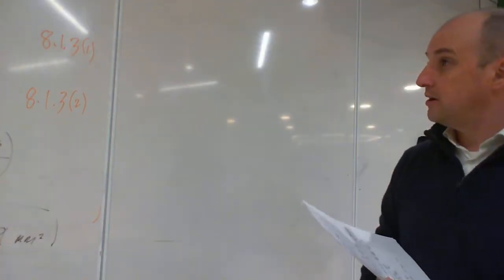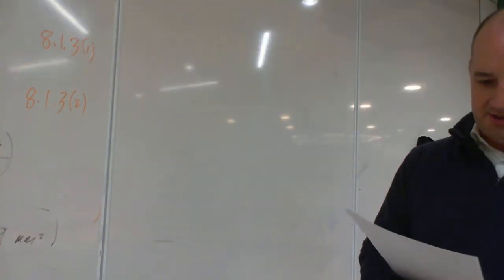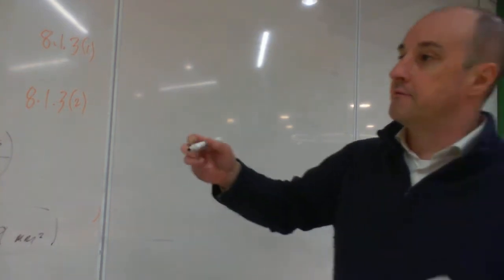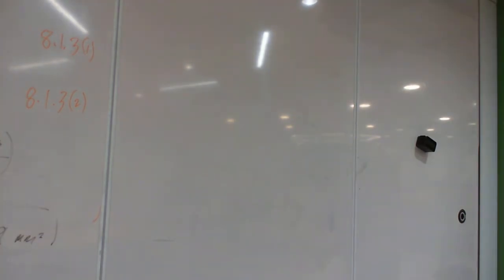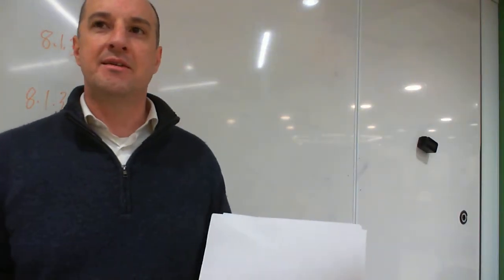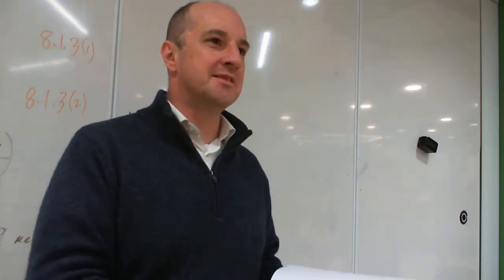Okay, so we've got that mu naught equation. And now the phi factor is another factor which has changed in the new code. The phi used to be an easy 0.8 or 0.6, and now they've made it more complicated, and it relates to what your Ku is. Okay?